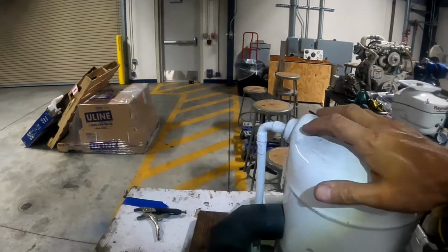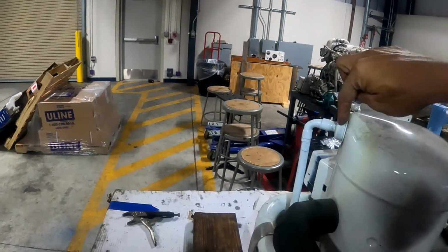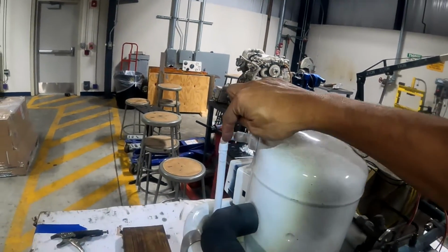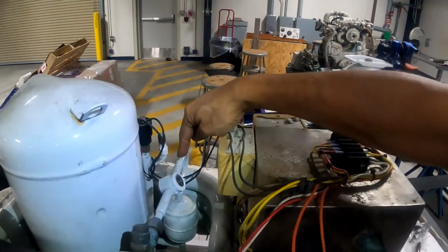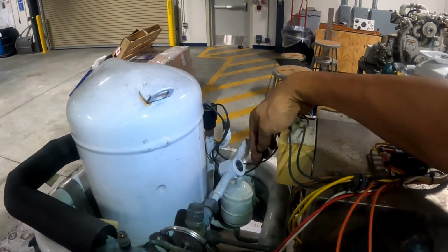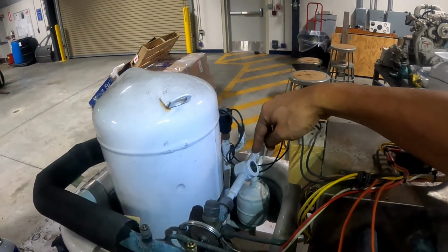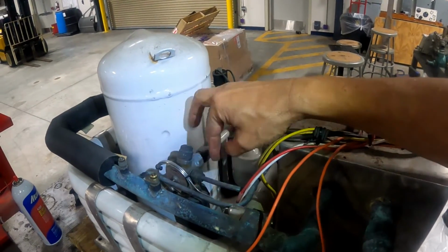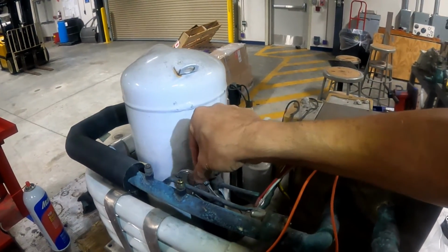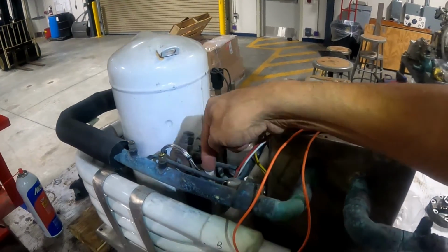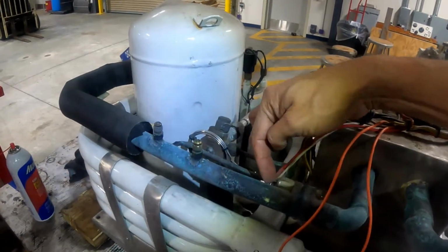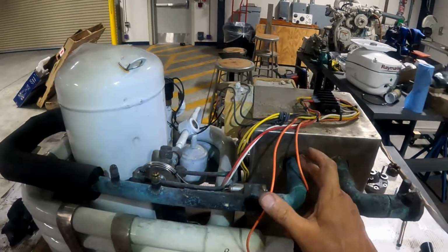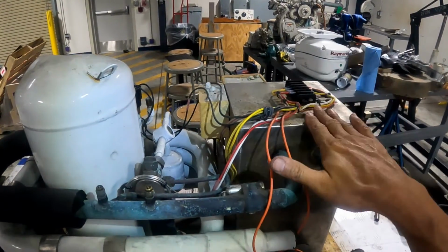This is the compressor, high pressure at this point, high pressure and high temperature, supersaturated vapor. The supersaturated vapor goes down, enters into the accumulator, and in the accumulator right now it is liquid, high pressure and high temperature. This is the thermal expansion valve. The thermal expansion valve receives the signal from this capillary pipe, and this capillary pipe is connected with a bulb, and the bulb is touching this pipe. This pipe is the return, the output of the evaporator.